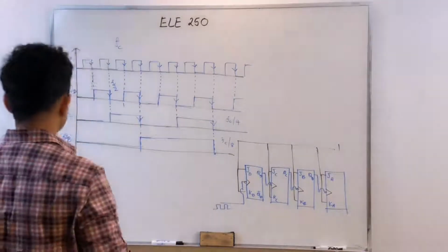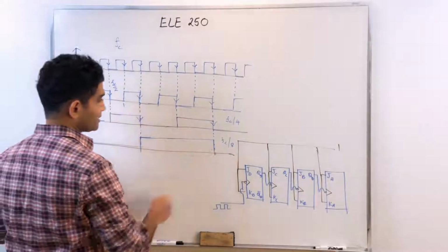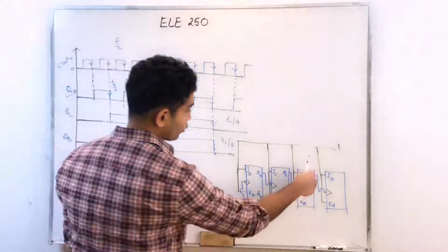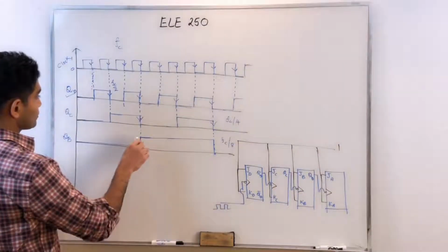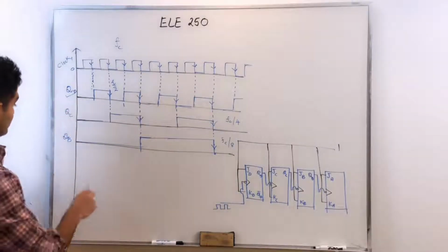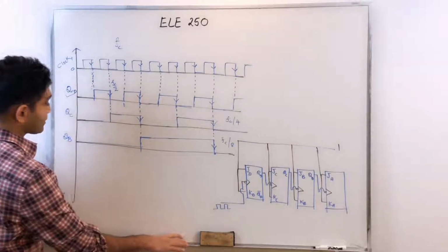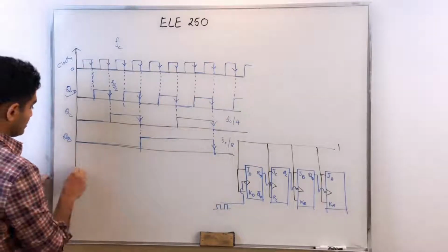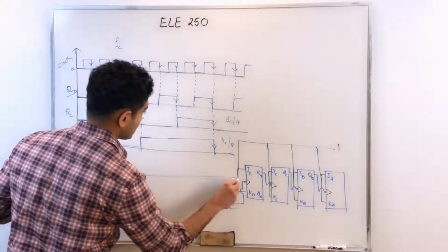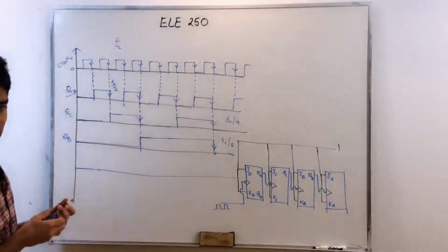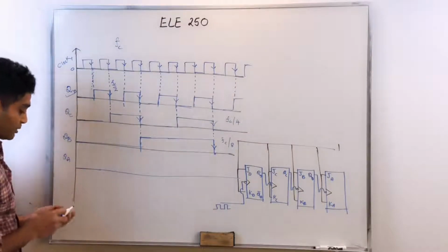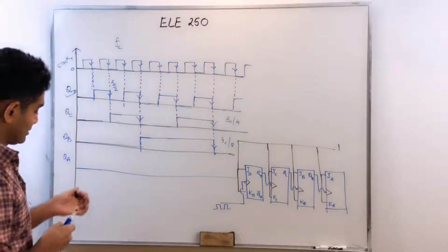All right. So QB, the frequency is FC over 8. I can do exactly the same thing for JA, right? In this case, my QB is the clock to JA. So these are my active edges for my JA flip-flop. So if I want to plot my QA, all right, let's assume that QA was also 0 to start with. What do I get?